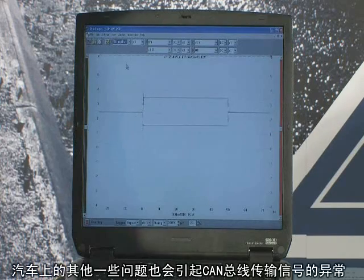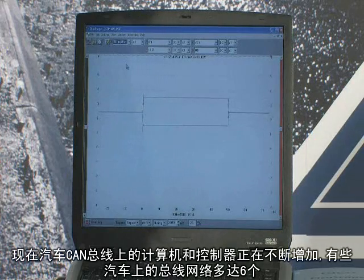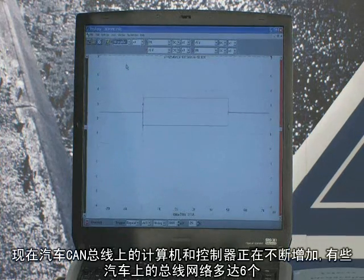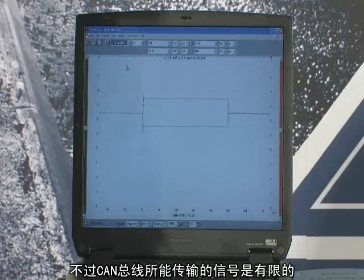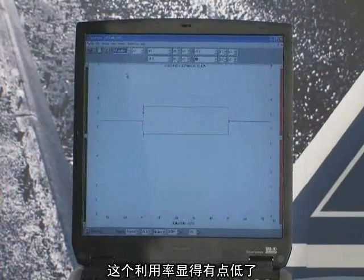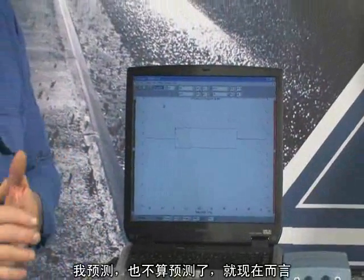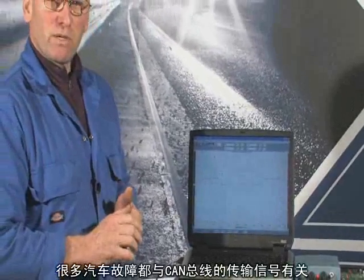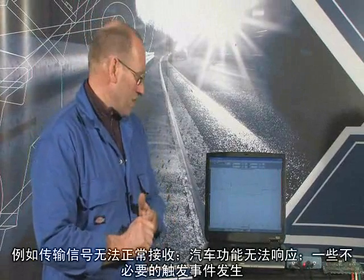Other issues, of course, with the motor vehicle that cause these types of errors: the manufacturers now are adding more and more computers, more and more controllers on various networks. I've already mentioned we can have up to 6 networks. A network can become saturated with data at around 35-40% of the baud rate. So it's an incredibly low threshold before we get rejected messages. And I predict, in fact, not just predict, it's actually happening now, many of the large manufacturers have an enormous problem with CAN transmission data affecting the functionality of the vehicle, where messages are being rejected, and you get random events happening on the car that were never intended by the driver.